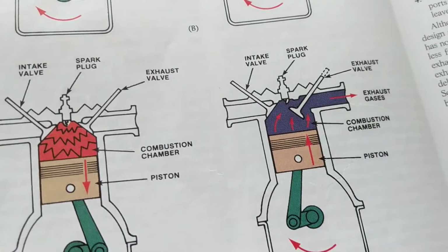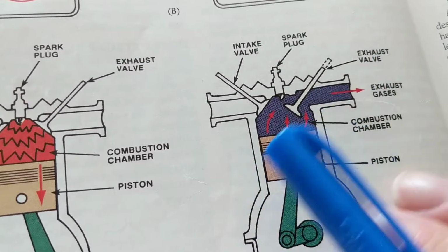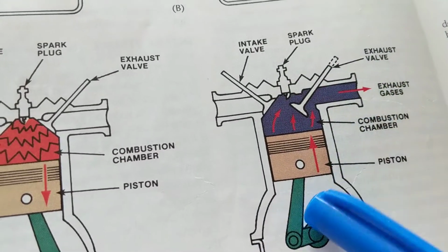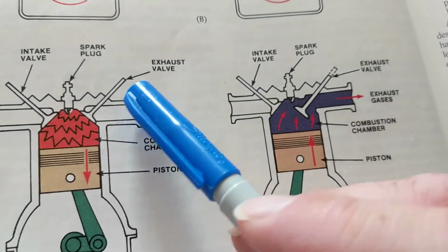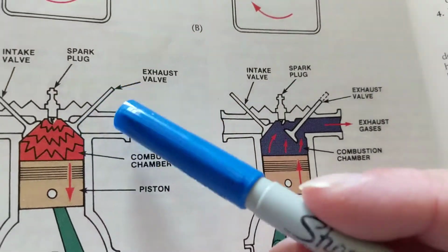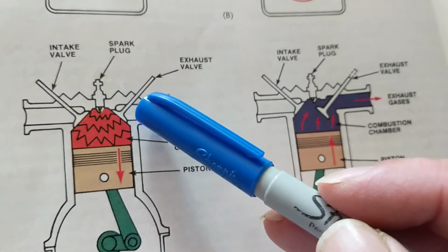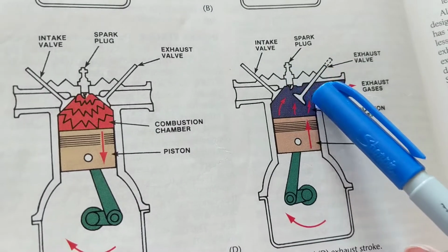That we'll talk about, like I said, in a minute. It did its job. We got to force what's not needed now, the exhaust, the byproducts of it, out of the engine, out of the cylinder. In order to do that, guess what? We need an exhaust valve. The exhaust valve opens. You see, it's off its seat. It opens. This is closed. Compare. This is open. See?